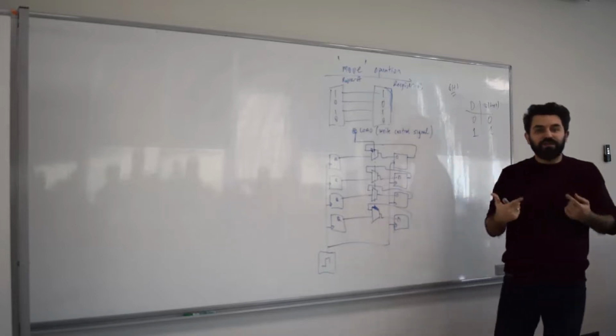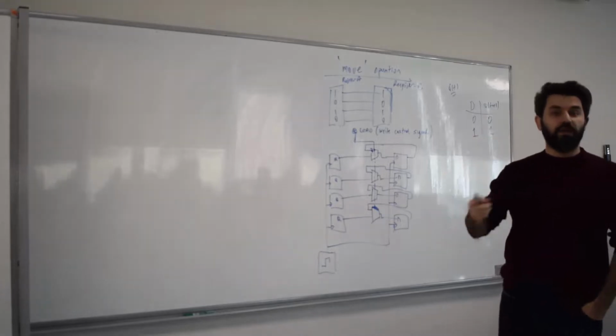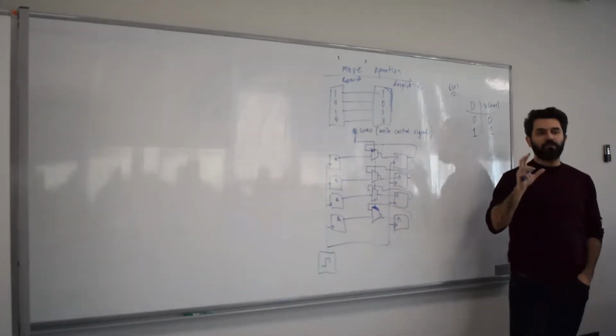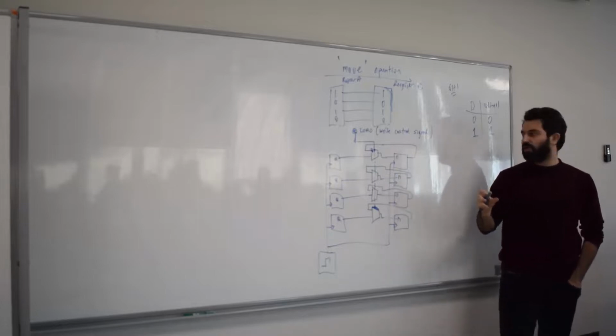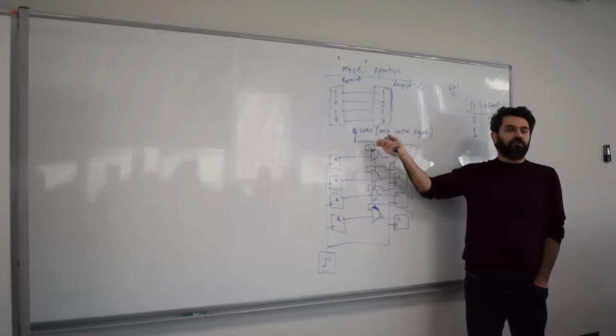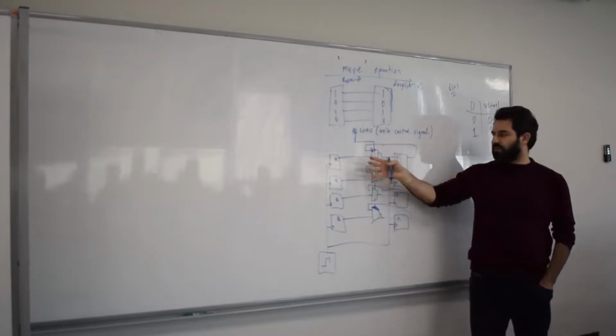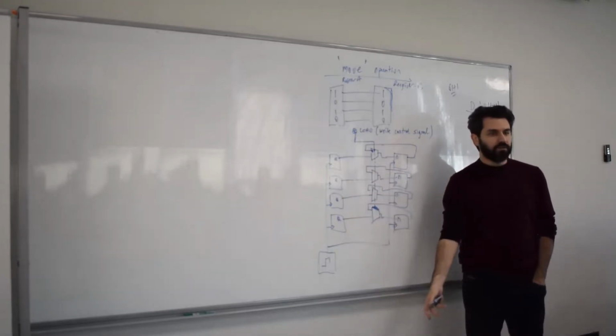The timing, for example, is a problem. In many cases that creates something called a race condition. So writes are problematic in any engineering, computer engineering application. That's why we have a control signal for writes, but we don't have one, for example, for reads. Reads could be anytime; you can just connect anything here and then read the value, okay?